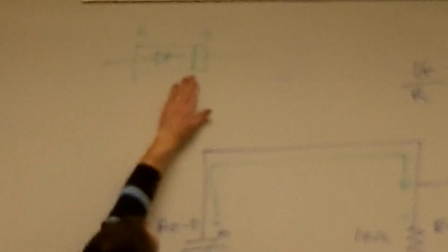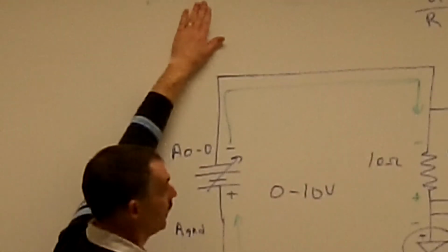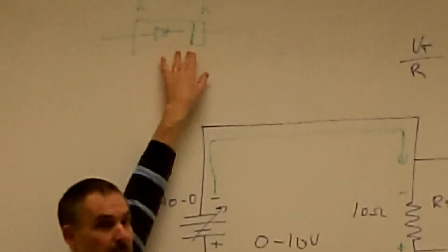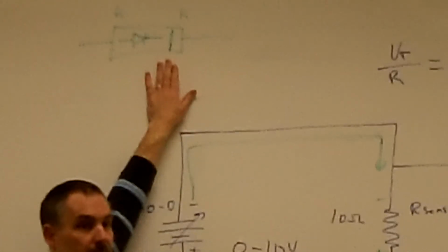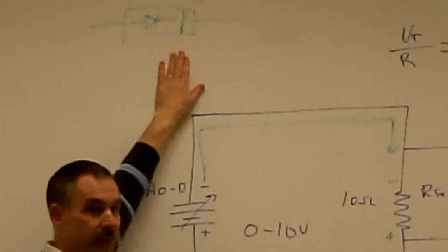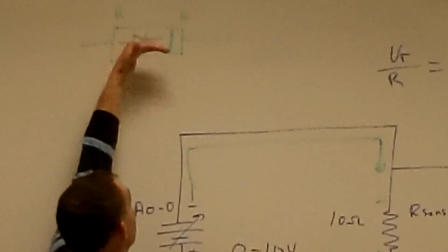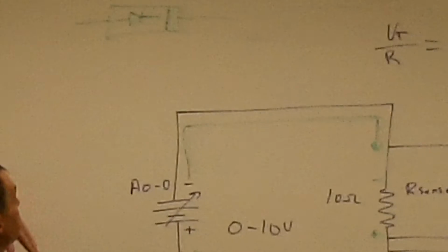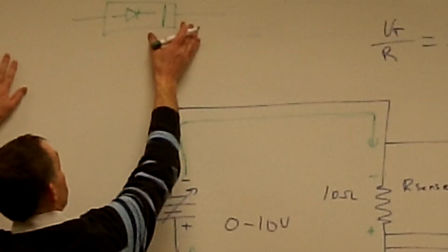Well, if we can't see where that black line is, sometimes it's hard, especially on those glass diodes. I think the ones that you got, the 914s, are your glass diodes, right? Yep. Otherwise, sometimes the 914s can come in black casings and stuff. It really doesn't matter. The casing that you're looking at isn't part of the diode itself. The material is inside that casing. But sometimes it's hard to see that black line.